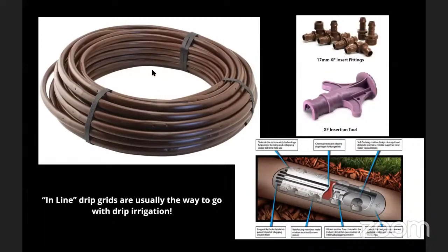One quick installation tip if you are working with this stuff that I don't want to forget. Most brands these days come covered in shrink wrap, and then you also have these plastic bands around it. The black here might be white. If it comes covered in shrink wrap, don't remove all of that when you're getting started. You can just cut with the scissors carefully so you don't cut your drip line, cut the inside of these bands, leave all that plastic wrap on it, and then you start unrolling these from the inside, which makes it a lot more manageable.